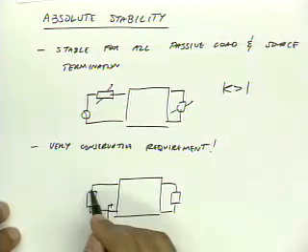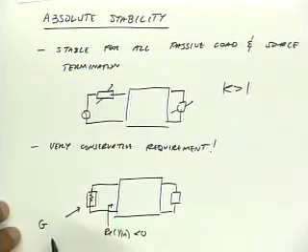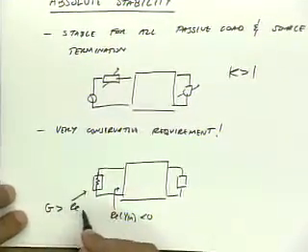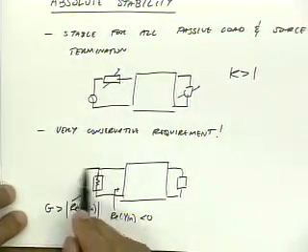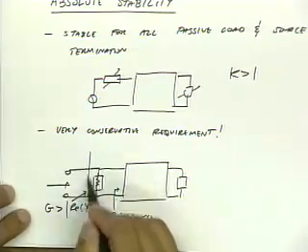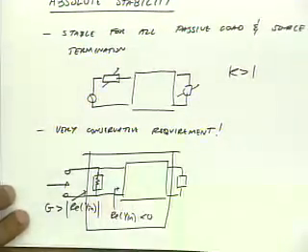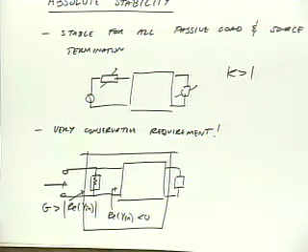If I just add a conductance g which is bigger than the absolute value of real part of y in, then the net conductance now looking into here is positive. So I've created a new 2-port that's unconditionally stable. Okay, and that's actually an important concept. It's going to let us define power gain for systems that are not unconditionally stable.